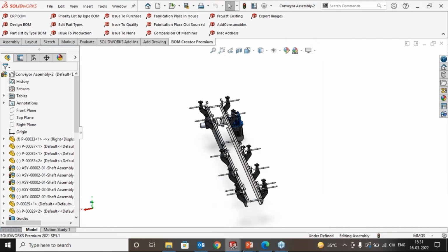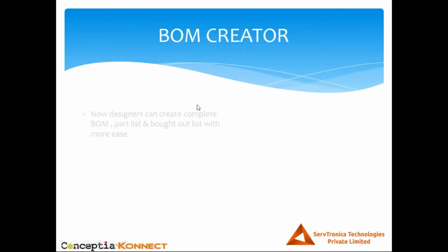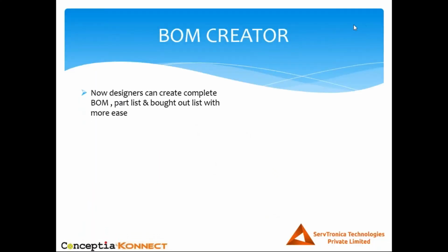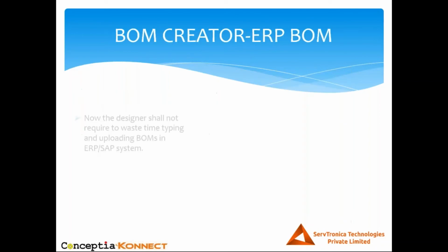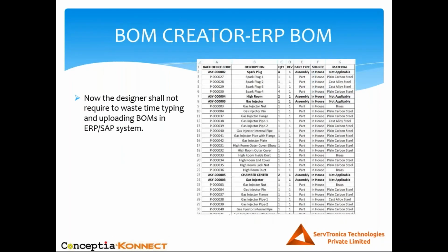Okay, so let's go ahead further. Now with BOM Creator, designers can create complete BOM parts with more ease, right? And the most important thing is we can create it during the design phase itself. So we need not wait for releasing the drawings. We can prepare the BOM as soon as my 3D is complete, right? And uploading the BOMs in ERP or SAP system is very much easier now. With a click, you can upload the information, right?